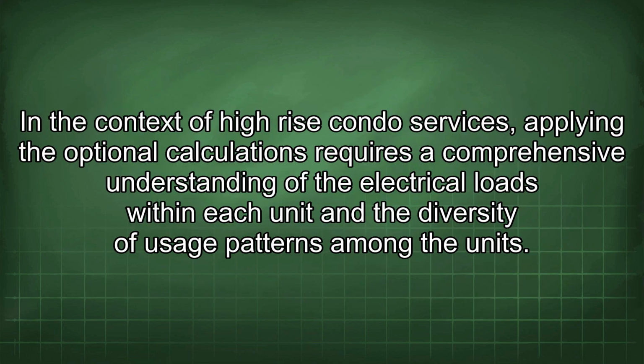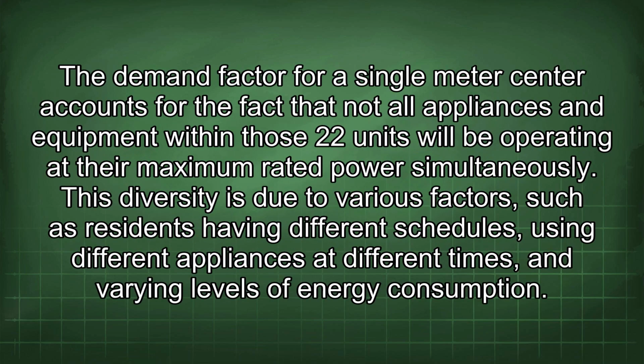In the context of high-rise condo services, applying the optional calculations requires a comprehensive understanding of the electrical loads within each unit and the diversity of usage patterns among the units. The demand factor for a single meter center accounts for the fact that not all appliances and equipment within those 22 units will be operating at their maximum rated power simultaneously. This diversity is due to various factors, such as residents having different schedules, using different appliances at different times, and varying levels of energy consumption.